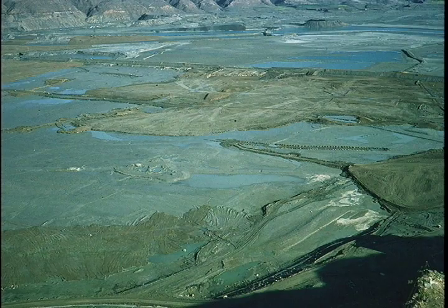The blanket had settled appreciably under the difference in water pressure between that on the top of the blanket and that on the bottom. This difference in pressure varied from 0 at the upstream end of the blanket to close to 300 feet of water at the downstream end. Because of the non-uniformity of the foundation strata, an undulating settlement pattern developed. Tension cracks developed along the center line of the ridges in the pattern, and linear compression zones along the valleys in the pattern. The compression zones were evident only in the soft clay silt covering the blanket.